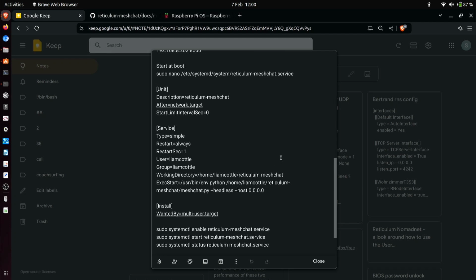And what I'm going to do is install the Raspberry Pi operating system headless. That's what they call the light version on the Raspberry Pi installer, because I don't need to have a monitor and a keyboard plugged into that Raspberry Pi. It's going to be remotely mounted. So by having it headless, there's less overhead of software running, and I'm going to connect into it using SSH via the network. I've actually got the Raspberry Pi plugged in with an Ethernet cable because I don't want to mess around with Wi-Fi at the moment. Once I get it working, I would enable Wi-Fi later.